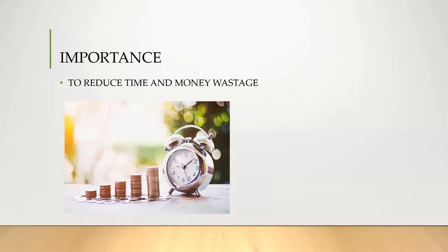One of them is how we will do the inspection. What is the better way of doing it? Is there any shortcut? Is it necessary to inspect every lot, or can some lots go without inspecting anything? So the concept of zero inspection comes in; at the other extreme you inspect all the goods, which comes under the 100% inspection category. In between come different sampling plans, deciding how many goods we should inspect. That balancing is very important.